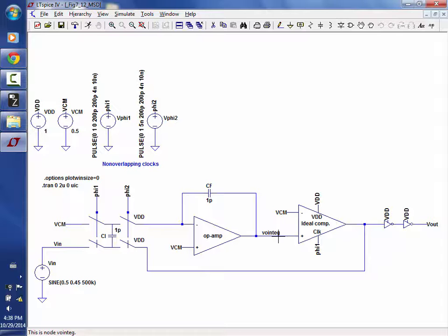Okay, so now we have to answer several more questions here. I want to talk about the op-amp gain, but before we do, I want to talk about comparator gain, offset, and all that. We have to ask, how big does the open loop gain of this op-amp have to be? Because if you look at the open loop gain of the circuit in chapter 9 that I put in there for the op-amp, it's not very high. So why don't we pause and you tell me how to determine the open loop gain of that circuit.